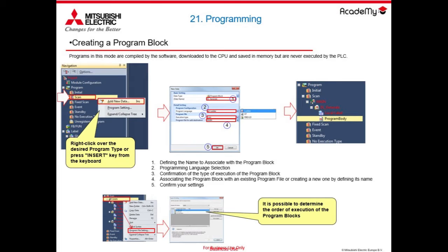For this project, we will define our R04 CPU as the hardware configuration, because once the code has been compiled, we will download it and write it to the PLC. In my case, I am interfaced to a rack with the sole presence of the R04 CPU, so let's exclude the modules that we had previously added in an example hardware configuration.